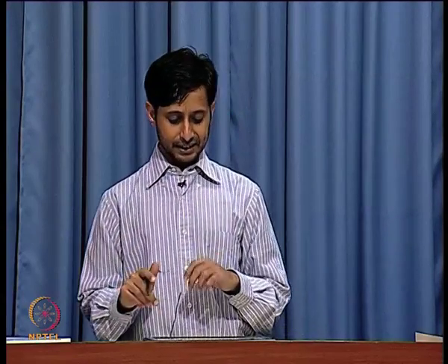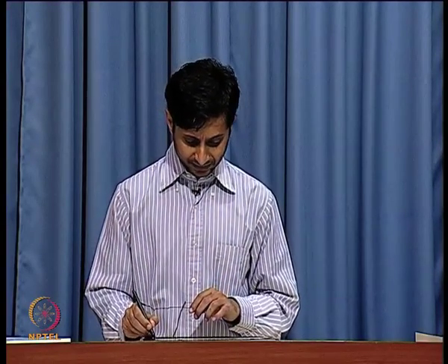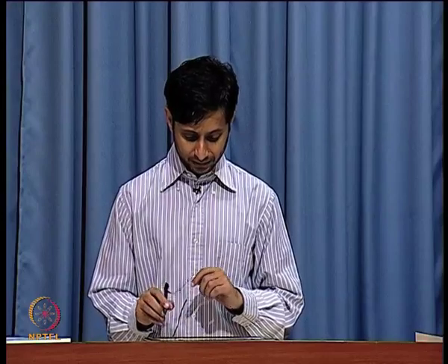And what is Z_out? Do I need to know Z_out? Yes, I need to know Z_out. Z_out is r_ds in parallel with C_db.